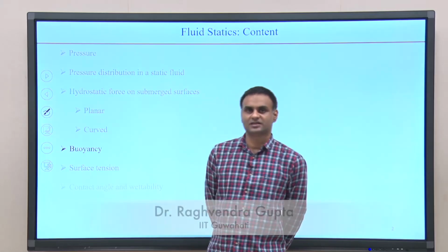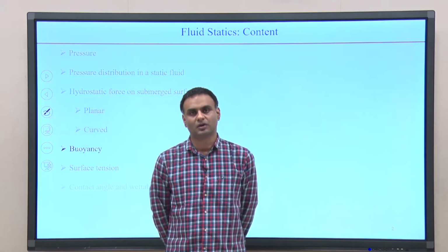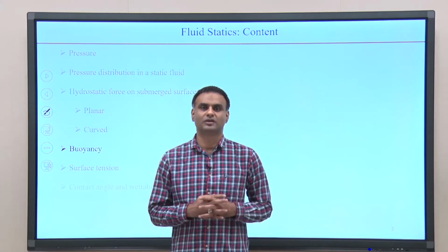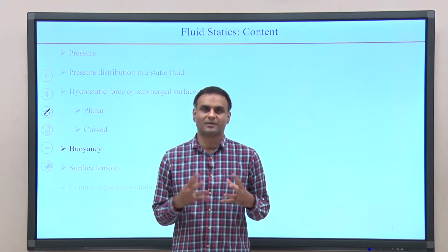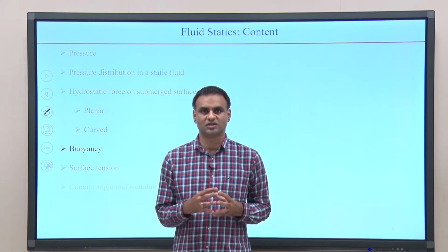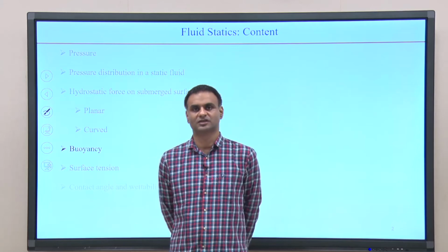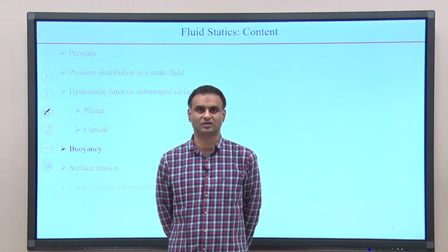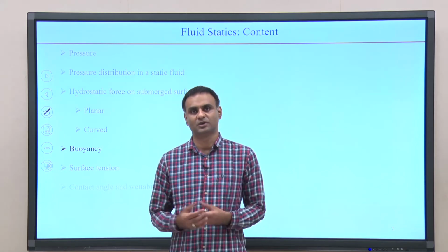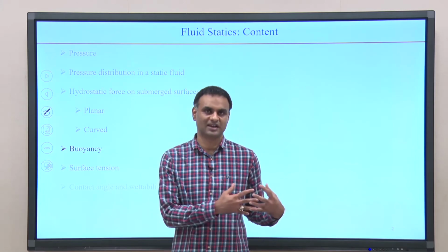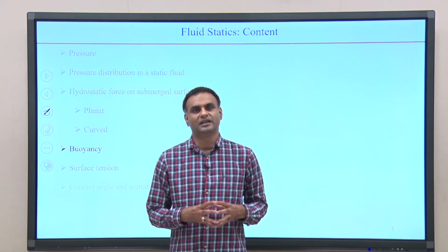Hello. So, in this lecture, we will continue our discussion of hydrostatics. In the previous lectures, we looked at the derivation for the famous equation P is equal to rho g h, where h is the depth below the fluid surface or the liquid surface in general, because we experience the hydrostatic force more commonly in liquid, because that is where it is predominant, but we also experience it in gases.